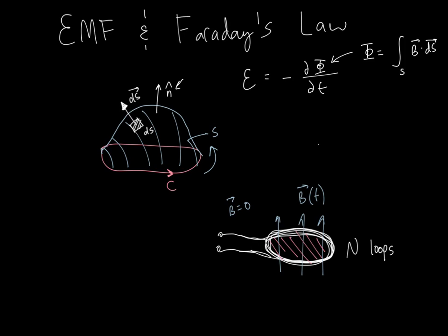So what's happening is we've got some magnetic field changing in time, and each of these loops is going to be generating an EMF. So it's almost like if you expand the loops, it's hard to draw actually, kind of like this. Each loop is going to be generating EMF, and the EMF is equal to -1 times the time derivative of the magnetic flux.